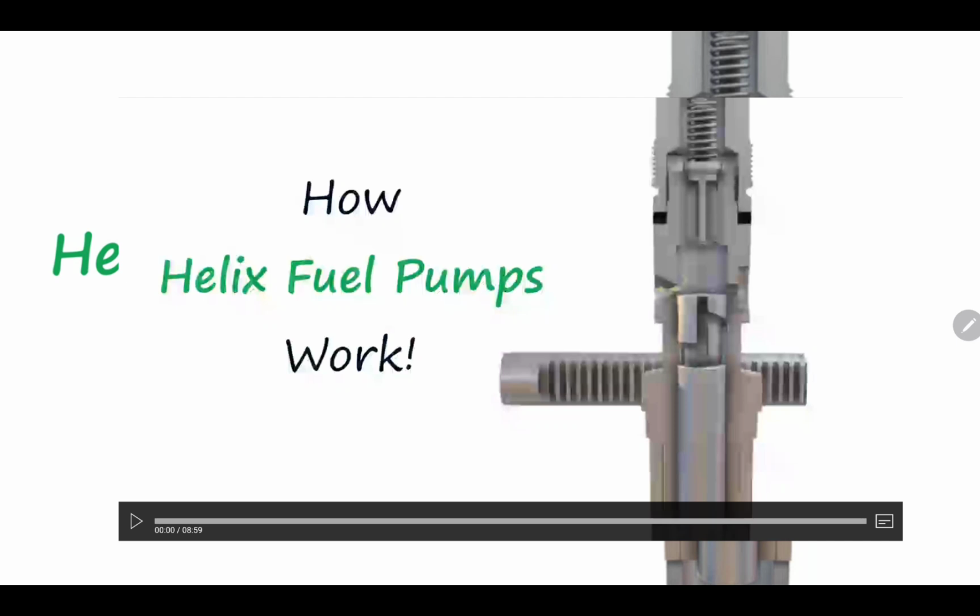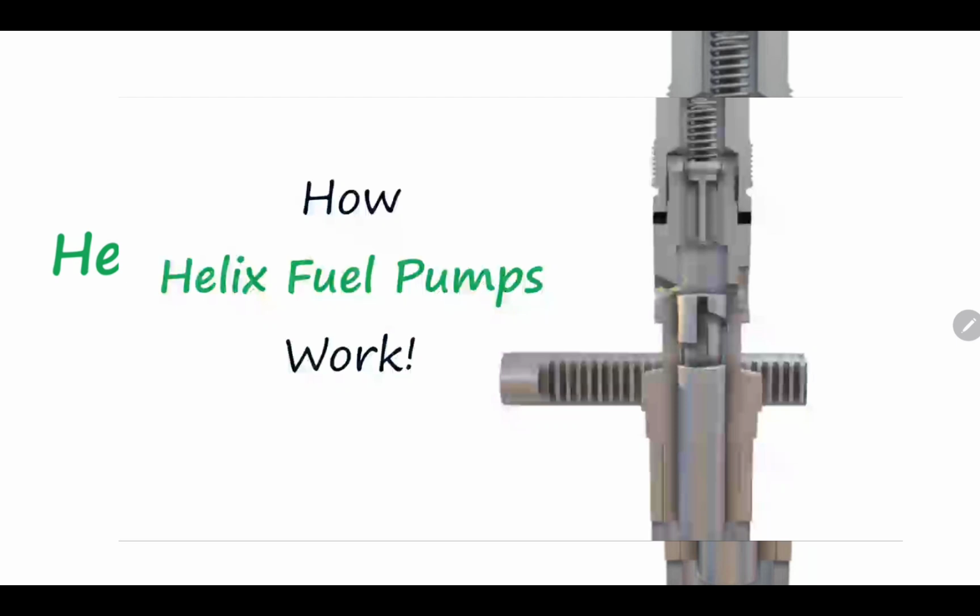The plunger is at its bottom dead center. And according to this video, this is the inlet port and this is the exit, the return port. And this is the delivery valve, and the injected fuel moves up like this.